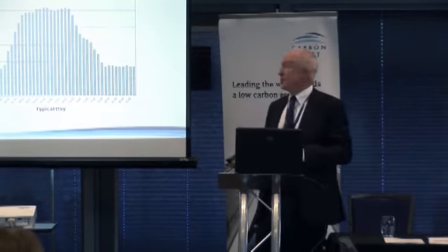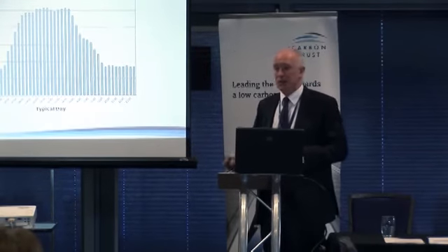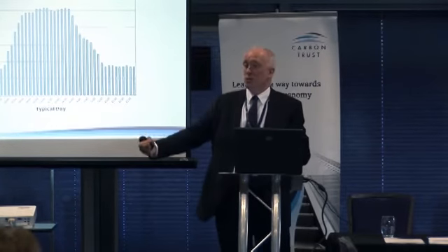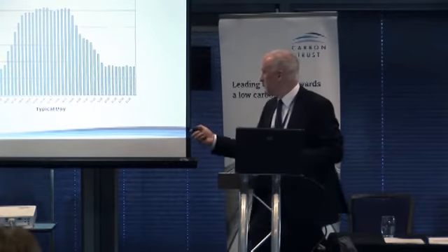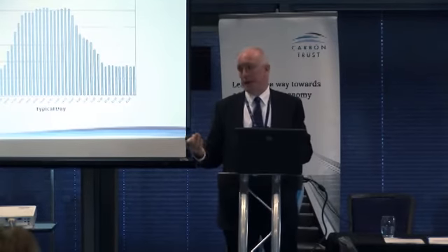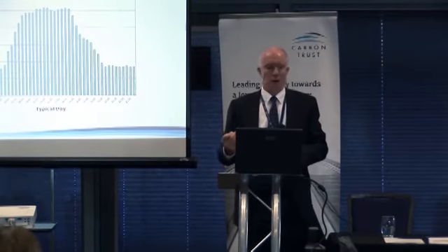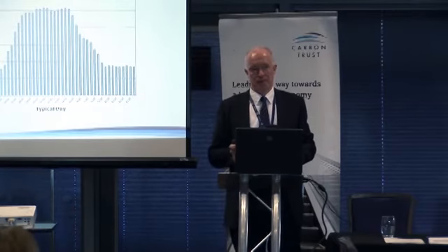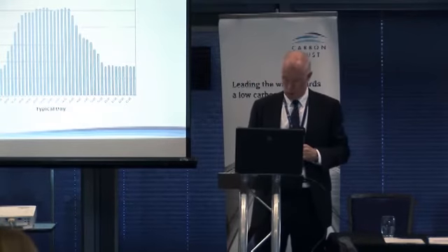But the key thing here is, why are we using 160 kilowatts overnight, and on Saturday, and on Sunday, when nobody's there? If you're 60 hours a week in your office, you're 108 hours a week not there. And if you're leaving this sort of quantity of energy on for the 108 hours a week, clearly it's a huge amount of waste. It's not uncommon for organisations to use 30–40% of their electricity when the building's locked up, because they're leaving things on. So it can make a very big impact, and you can get everyone working on this quite straightforwardly.